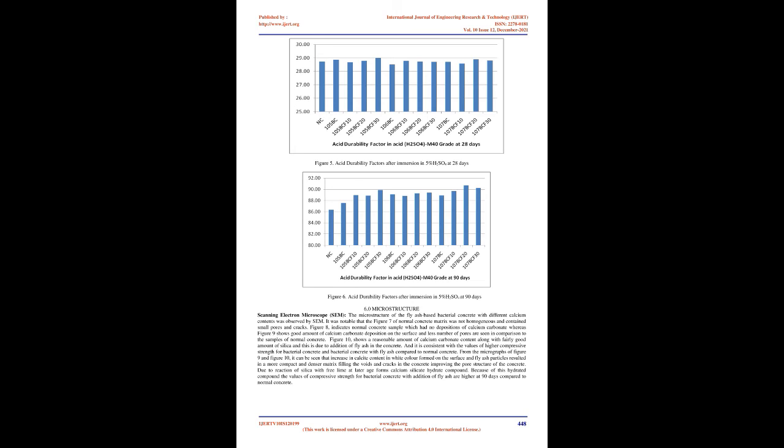Acid durability factor, ADF, can be determined as follows. 5. Acid durability factor, ADF, equals Sn/M, where Sn equals relative strength at n days, %; N equals number of days at which the durability factor is needed; M equals number of days at which the exposure is to be terminated. Acid attack test was terminated at 90 days. So, M is 90 in this case.